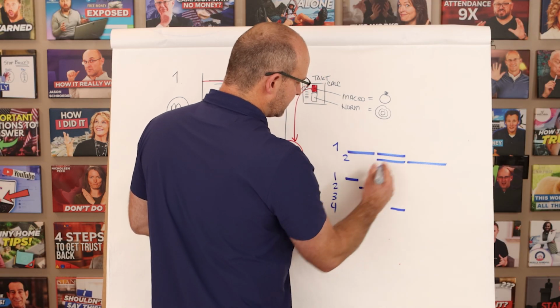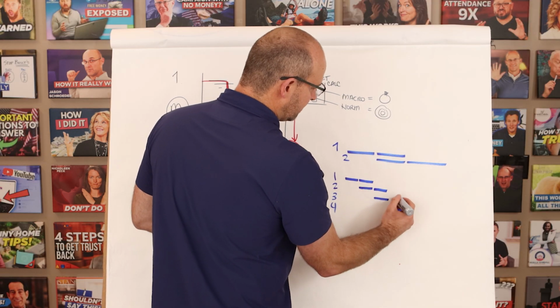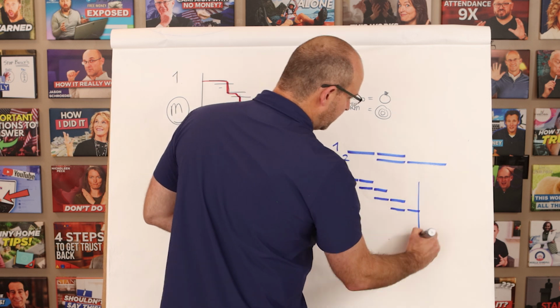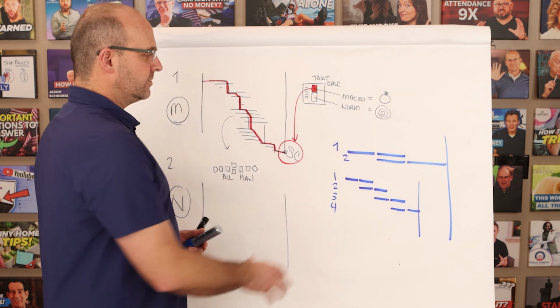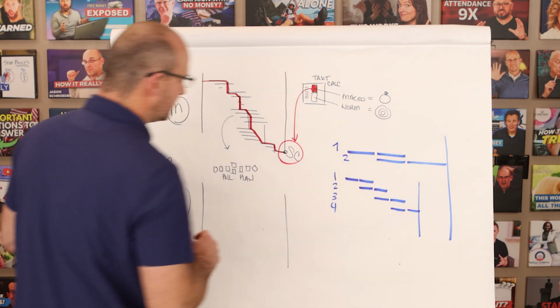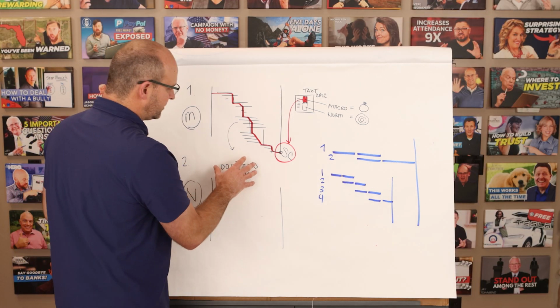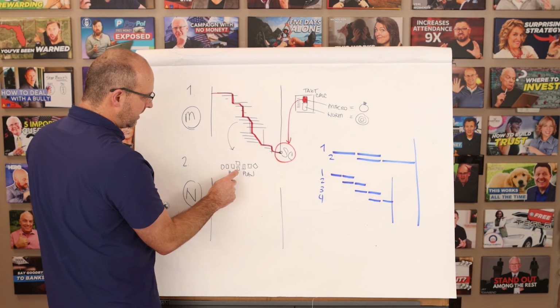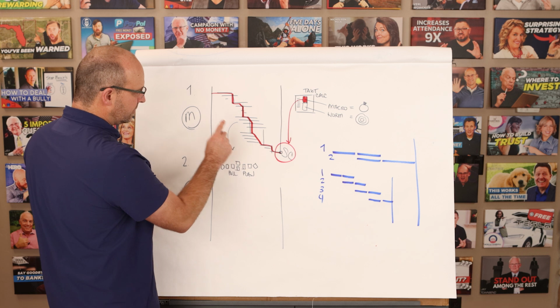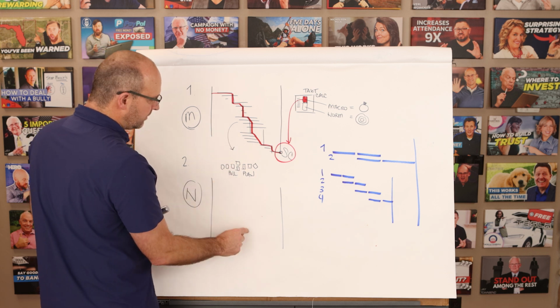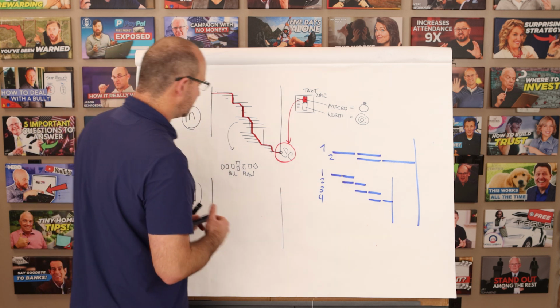And then when you add this second activity to it, that's going to be halved as well. And you have a different end date, right? So rezoning pulls your project closer. So the reason I'm talking to you about this is because by the time you do your pull plan and choose a new zoning strategy, you will be able to gain buffers for your contingency planning.